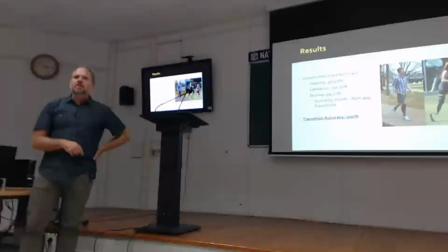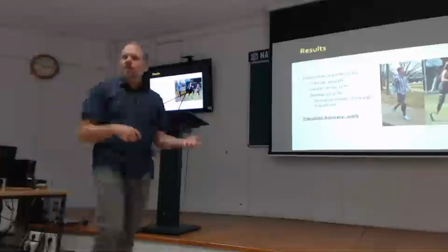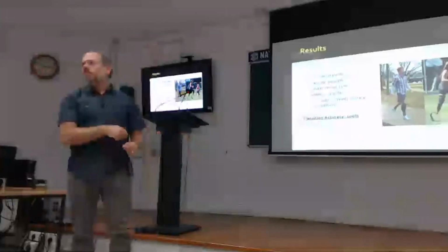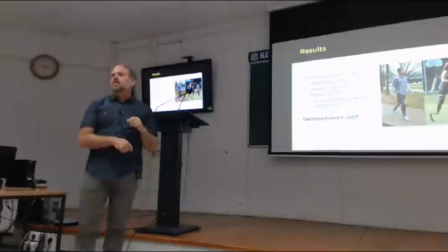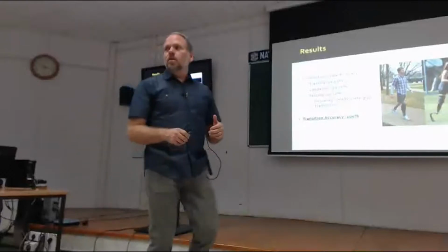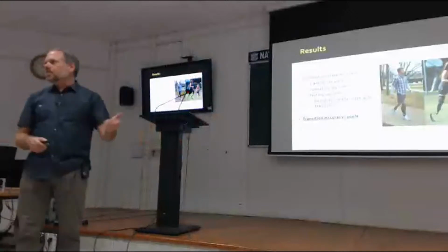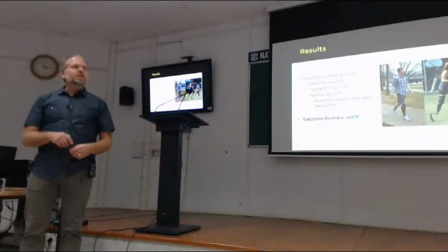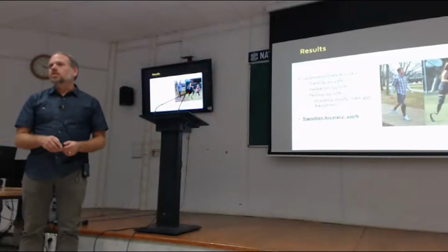So this is interesting. If I mispredict that the next step is still going to be a walk, it matters a little bit for stiffness. But if I miss the transition, then it's more critical. If I'm walking and I go to run, but the foot doesn't know I'm about to run, it doesn't know what to do, then I'm likely to stumble. And so we think this is more important even than knowing what the steady state predictions are.